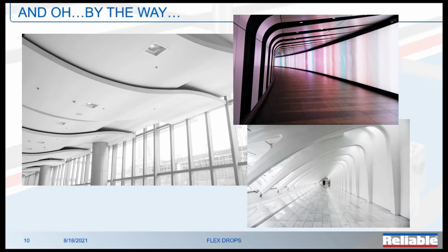And everybody's familiar with the issues around cloud ceilings and things like that. If you're in a museum, you might see an airplane hung below the ceiling. You might see a pterodactyl hung below the ceiling. One of the premier online retailers, in their office buildings, they like to hang doors below the ceilings on different angles and pitches. And so anytime, obviously, we're over 4 feet wide, we've got to get fire sprinklers below those. So now we've got this challenge of how to make all of that happen.